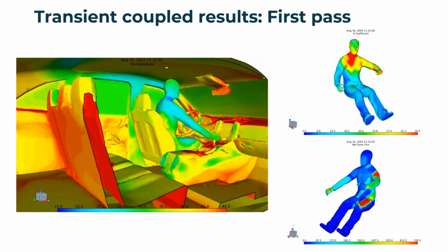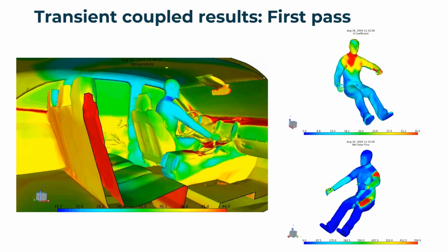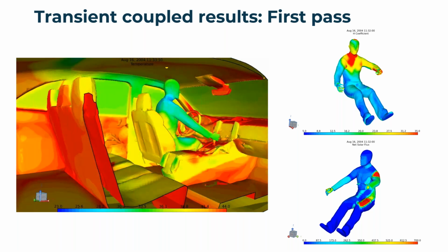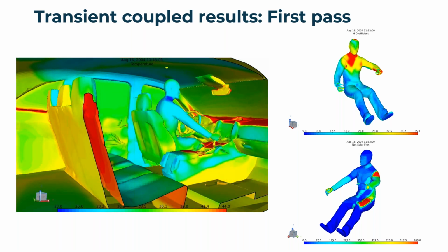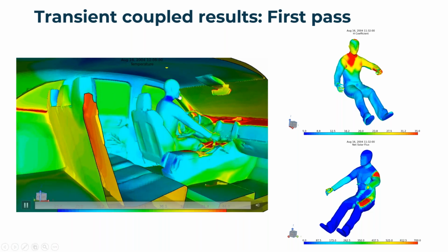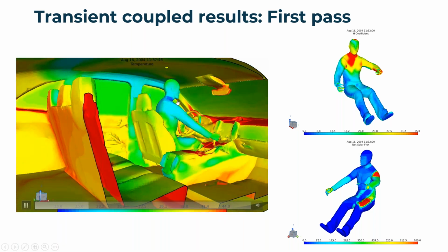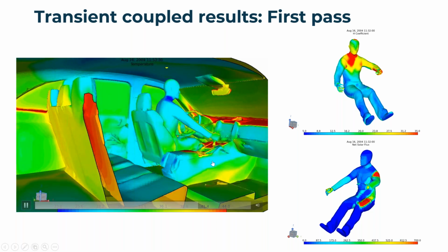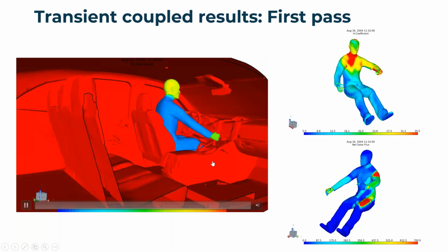After that simulation completes, on the left here, we have an animation of the surface temperatures from the TiTherm model looking inside the cabin with a clipping plane. You can see the temperatures cooling down from that initial hot condition. Especially here, on the human, on the neck and face, we're getting a lot of cooling with the HVAC flow aimed at that area.